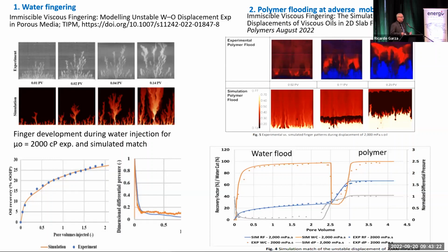And we see by this approach, and maximizing the mobility, we are able to get the breakthrough at about the right time. The number of fingers seems reasonable. And up to the breakthrough, we have a very good match in all respects. The problem is on the later stage, where we see that the fingers are spreading into channels, and it's spreading too much in that sense. But that's another issue. So on the early stage, we have a very good match, we think.